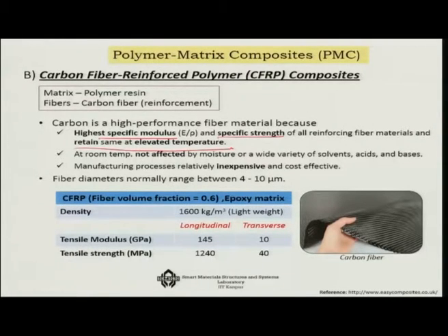GFRP by 200 degrees centigrade is of no use, whereas CFRP can be used at a much higher temperature. And at room temperature, it is not affected by moisture or a wide variety of solvents, acids and bases. But it is expensive, particularly the carbon fibers are expensive.